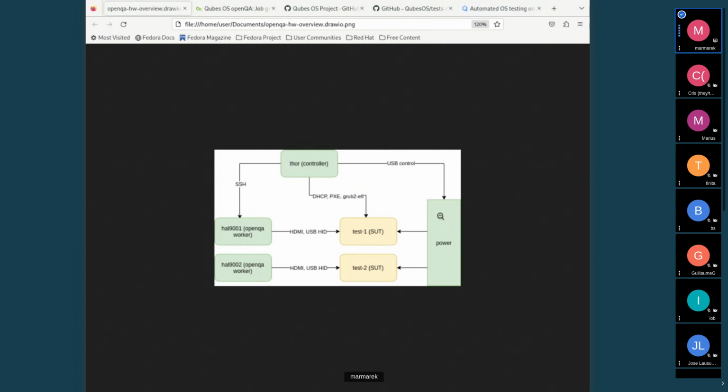Okay, so I have power control, user interface input, and capturing output. So what next? In the case of testing Raspberry Pis, the installation image or operating system was provided using an SD card, and there is this SD card multiplexer that you can use to switch the card between a Raspberry Pi and some other system to replace the content.